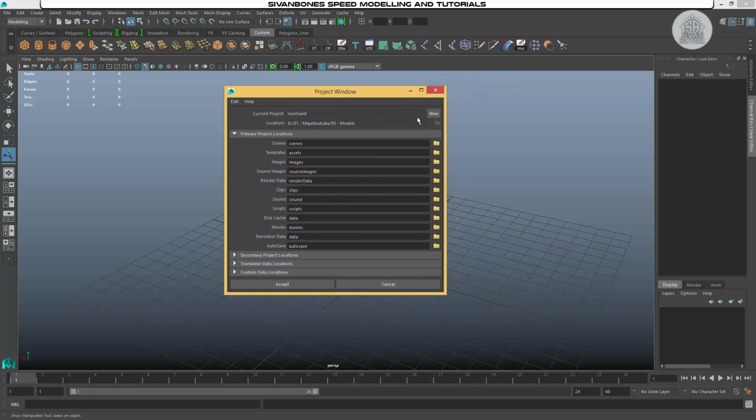Right, so the first thing is we have to click New. You want to give it a name, something that actually relates to what you're doing. So I'm just going to call it Creating Projects Test. You need to also set the location. The whole point of a project is that you can keep moving the project around. So this is just where you're going to create it for the first time. If you work in a company, they will have dedicated locations for it, and they'll tell you exactly where things are going to be stored. But for your own thing at home, just pick a location that's easy to get to or where you're always going to work from. This one for me is fine. I do all of my models in this location.